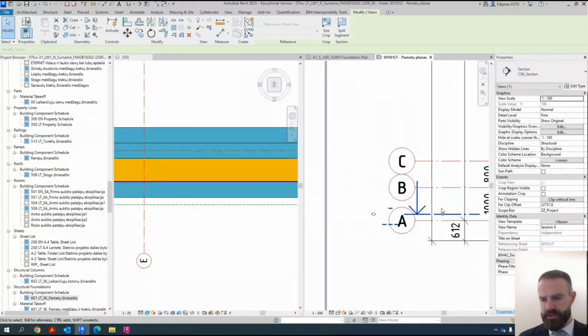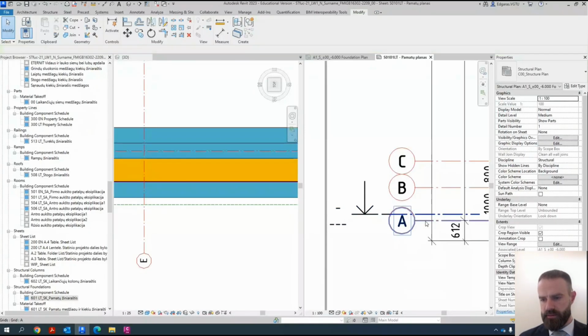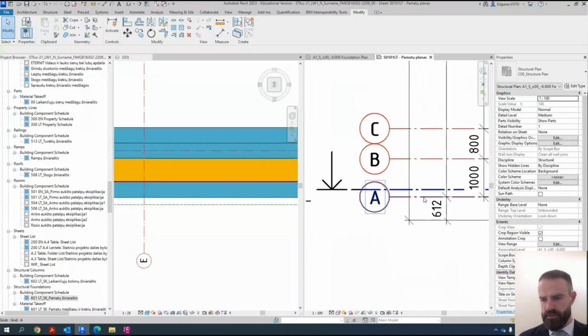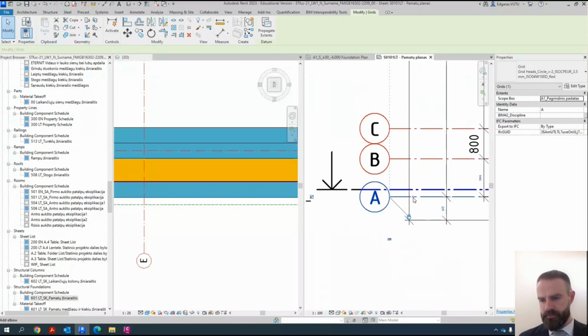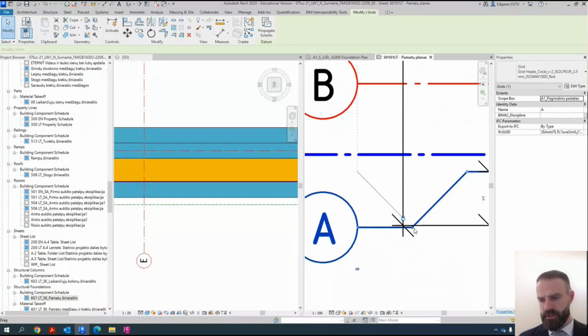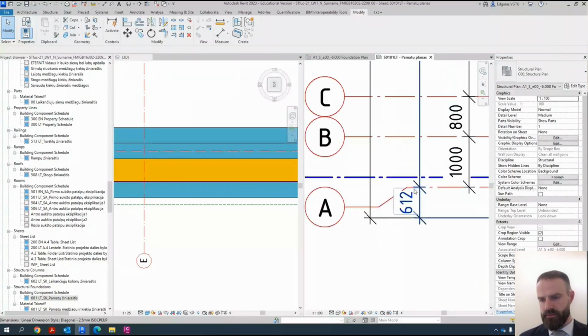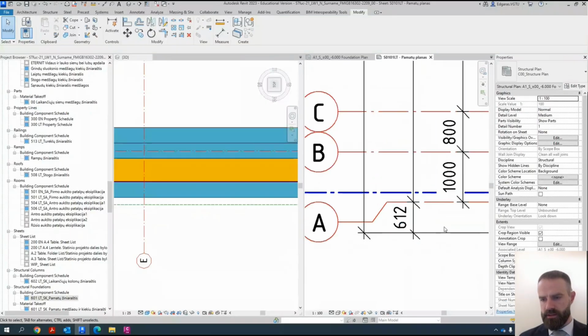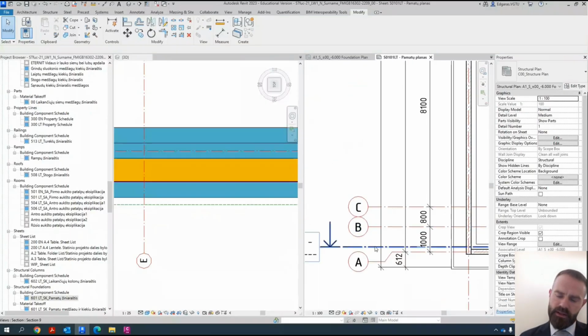And if we have a section line it should always go outside the bubbles. And if some objects are crossing each other, we can use this symbol to move object a little bit to the side and to organize everything so all the parts of the drawing are nicely readable and no parts are hidden.